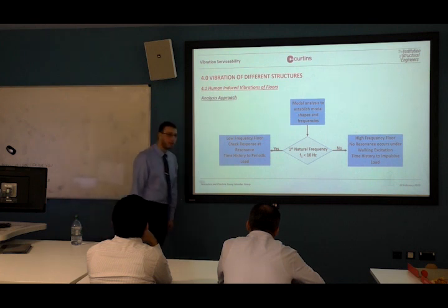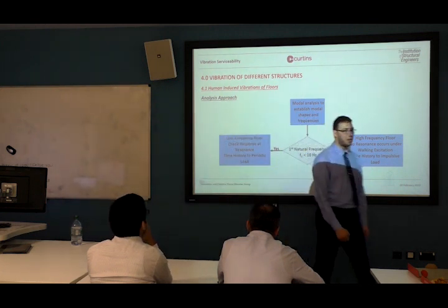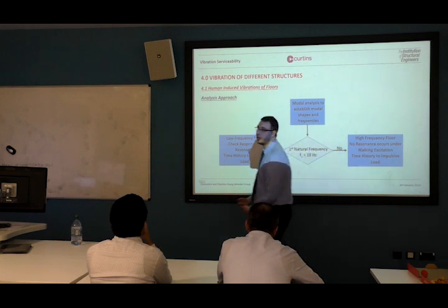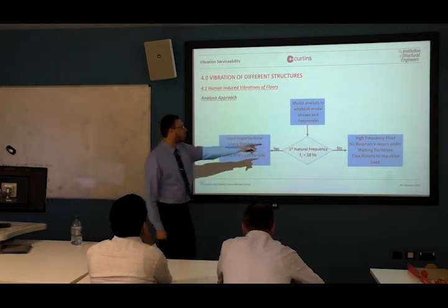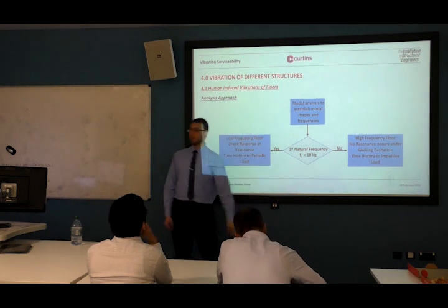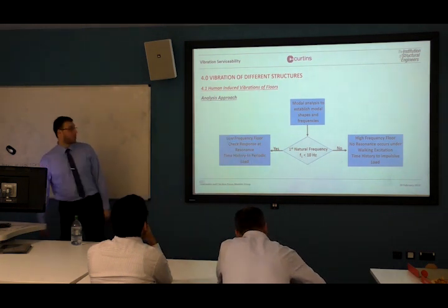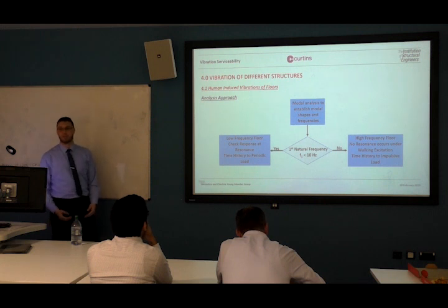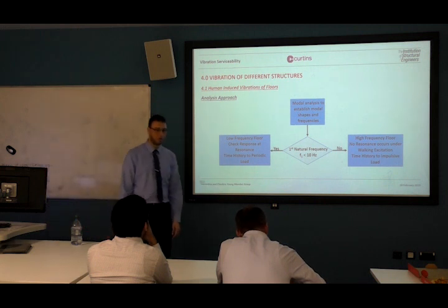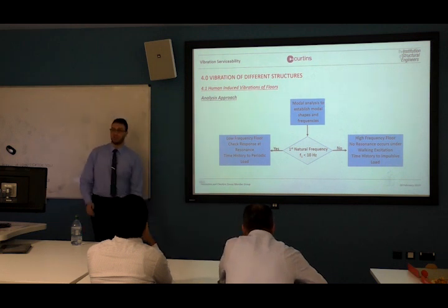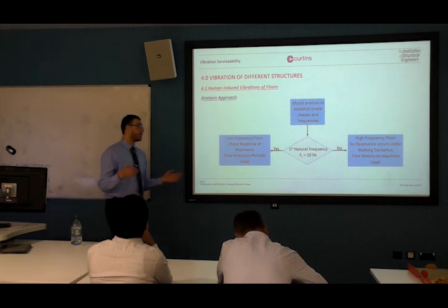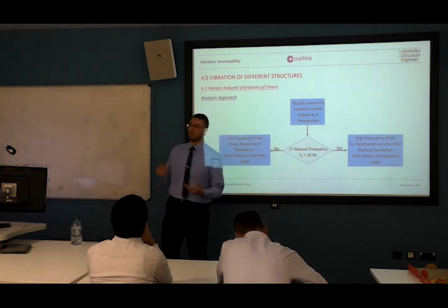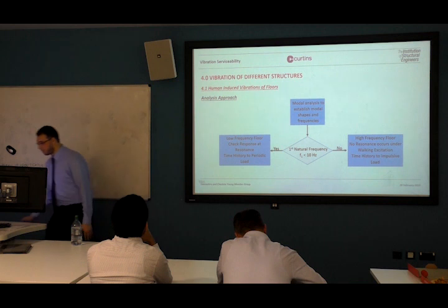You walk in, and by your walking you might cause some resonance in the structure. But the high frequency floors are affected by a type of load called impulsive. It's like, that's it. This is impulsive load, a very, very fast load, and it's going to cause the slab to vibrate at a high level that we wouldn't accept.